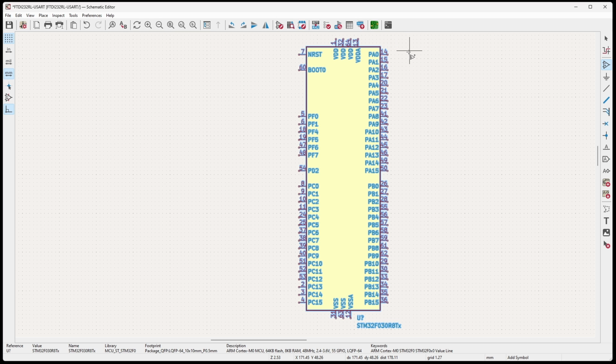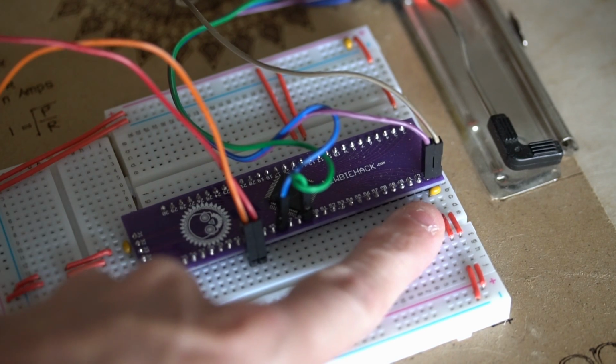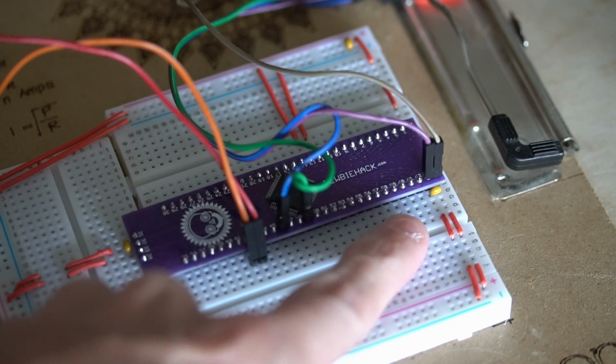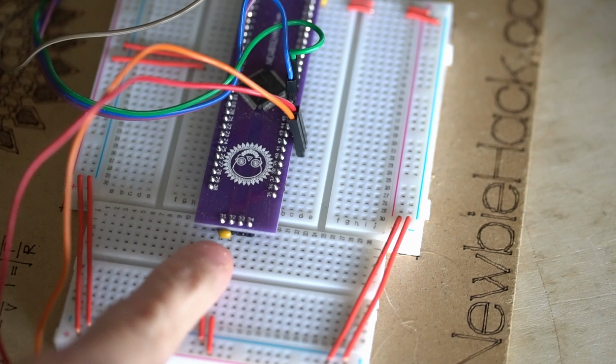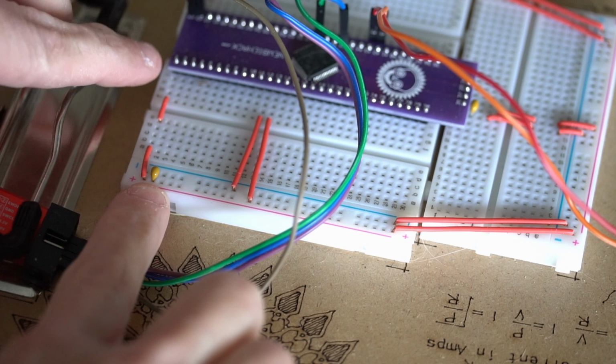The first thing we want to do is apply our decoupling capacitors that we already have on all of the projects that we do. So these are the decoupling capacitors I'm talking about. The one that is very close to the main power, the ones over here, the one over here at this location, and the one over here that is next to this power pin.